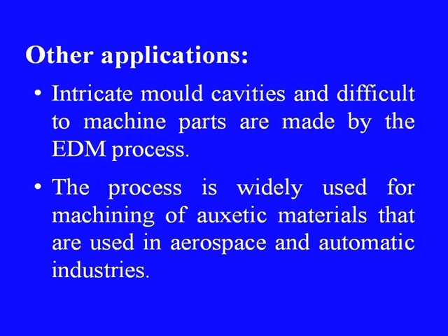Let us see some other applications of this WEDM process. This process is useful for cutting intricate mold cavities and difficult to machine parts. The process is also widely used for machining of exotic materials that are used in aerospace and automotive industries. EDM being a non-contact type machining process, it is very well suited for making fragile parts which cannot take the stress of machining. The parts that fit such profiles include washing machine agitators, electronic components, printed parts and difficult to machine features such as honeycomb shapes.